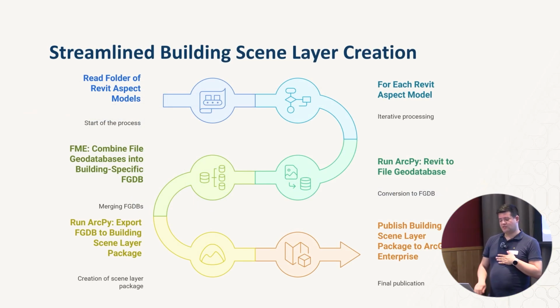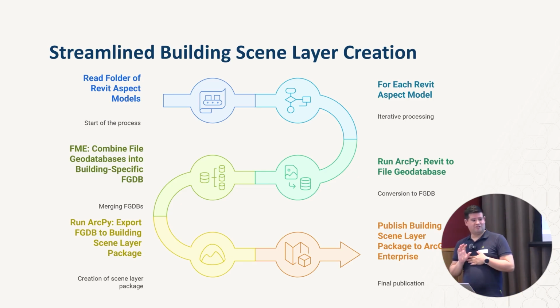But then we need to get it into ArcGIS. FME handles Revit quite nicely. ArcGIS has a very specific flavor of BIM they support. So I tried to do the stuff all with FME first, but then I figured out I'm still stuck with ArcPy. I have to find the definition that Esri uses. And what I do is here FME is my orchestration tool.